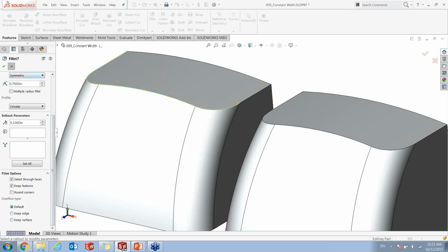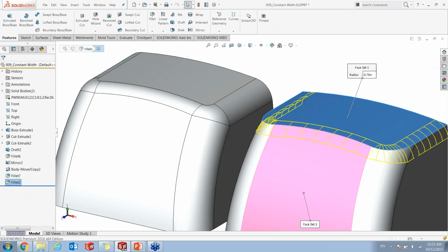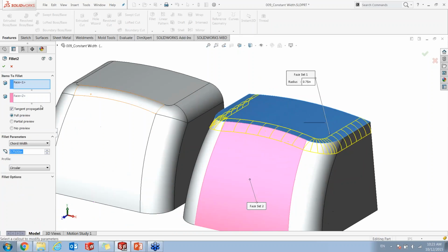But if I now use this face with a face fillet, you can see I selected two faces, and then I have the option we call cut width, where the system controls the vector for the cut width that you can see on the screen. So it is always the same size along the whole edges. Only face fillet can do this. The first example is a constant size fillet that does not have the option that allows you to control the cut width.